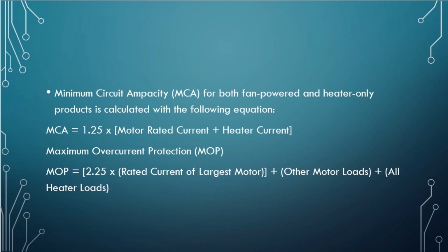The minimum circuit ampacity is also used to figure the minimum wire size required for field wiring. It is chosen to guarantee that the wiring will not overheat under the expected operating conditions. The wire size takes into account the normal current draw, aging of components, and anticipated faults.